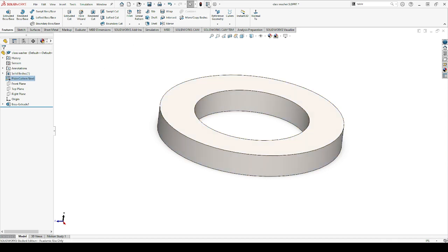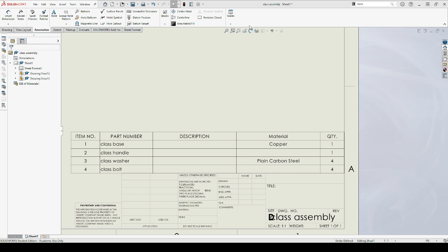And then I come up here to file properties and add in a new custom property again. This custom property is just going to be material, and the value for that is going to be the actual material itself. I'll hit OK, and then do the same thing. Save it, close it, watch it update, and as soon as I do that, now that I have everything set for the material, it'll automatically pop up here for the material.